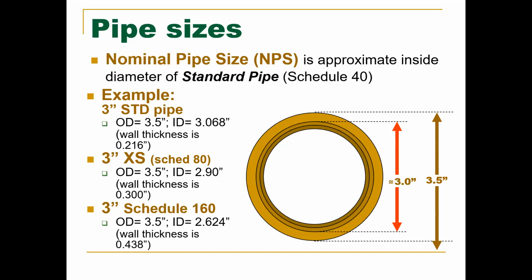The chief engineer is only going to be sitting there clicking on the computer to approve. He's not going to be looking too in depth. If you need a certain amount of feet of 3-inch Schedule 160 pipe, and you order just standard Schedule 40, you're going to have a really pissed off chief engineer because it's a waste of money.